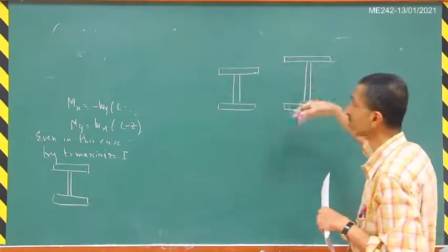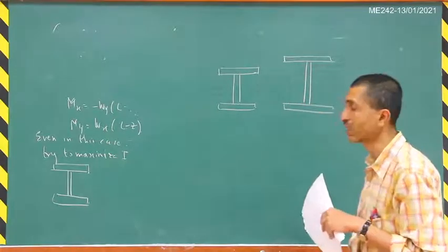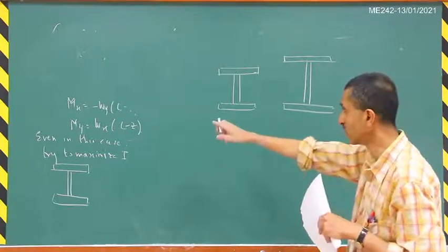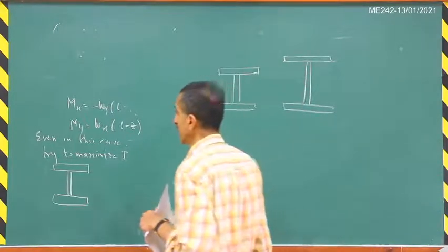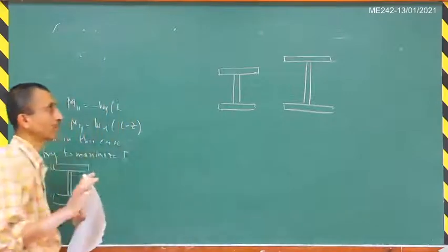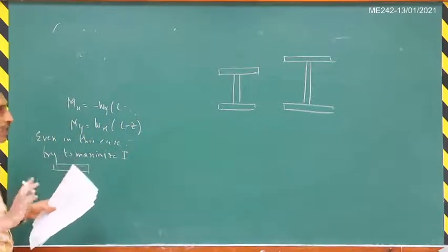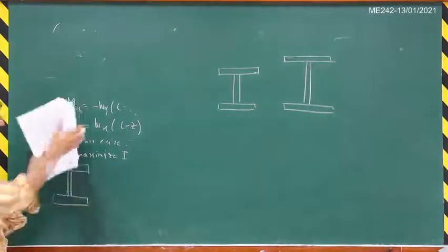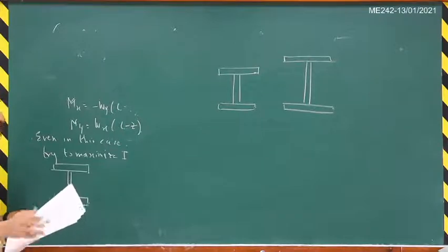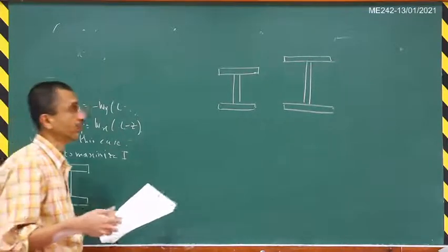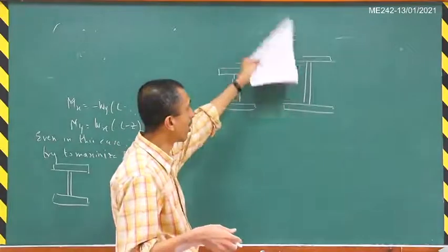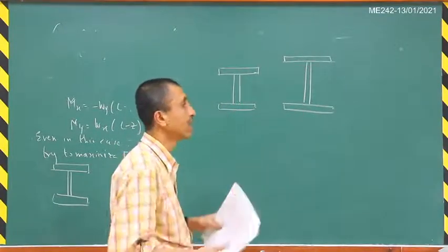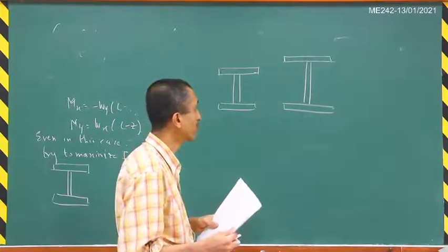You have to bring in other considerations such as buckling when you are trying to maximize the flexural rigidity. So it's a balancing act between the two. We cannot just indefinitely keep on increasing this I by simply moving the cross sections away from the neutral axis.